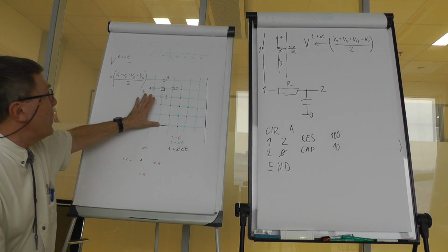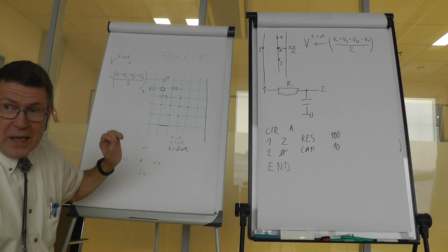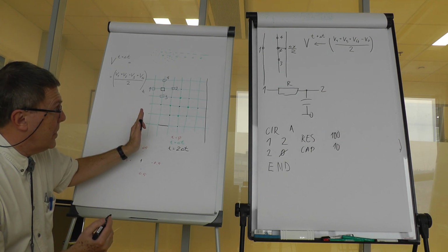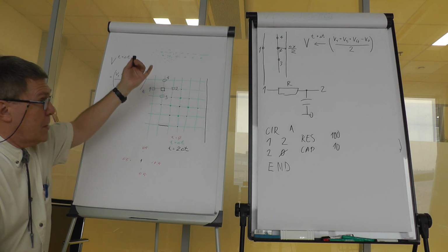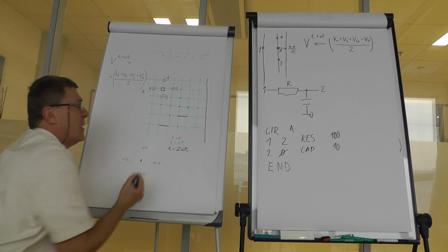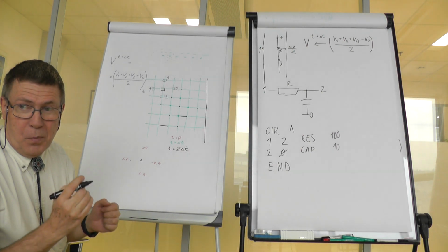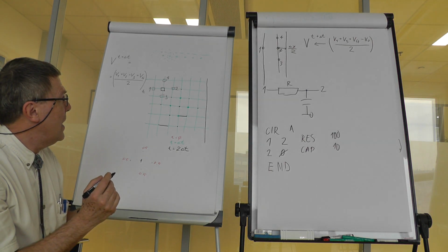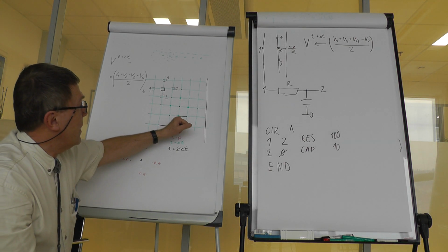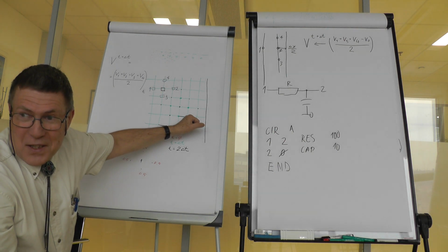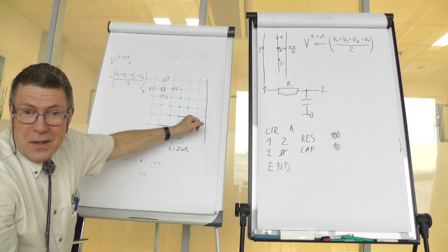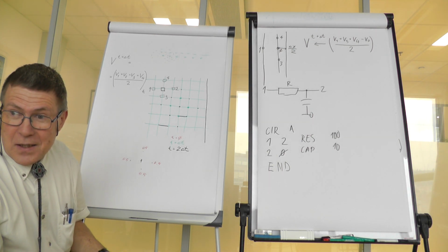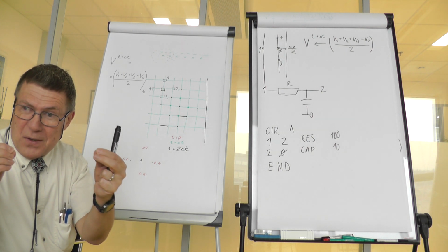And now the network equivalent of this situation is a grid where you have node voltages or nodes, and this element could be replaced by a transmission line section, which connects the 2 points, and the length of the transmission line is just chosen so that the propagation from here to here is the time of propagation of the signal through that piece of transmission line.